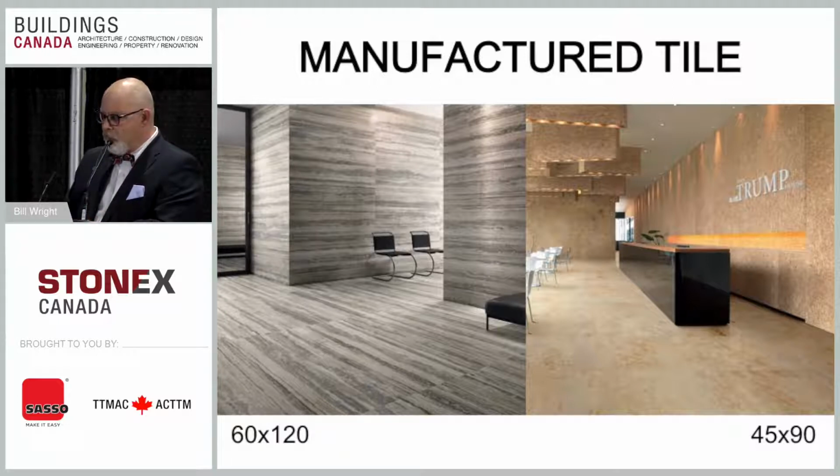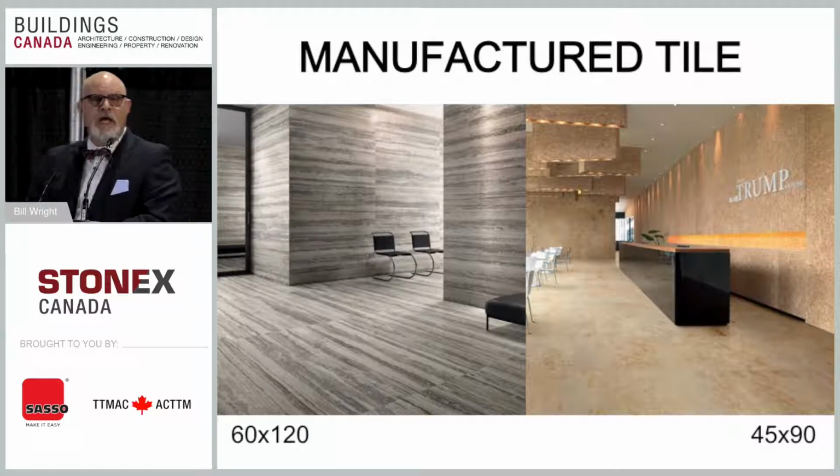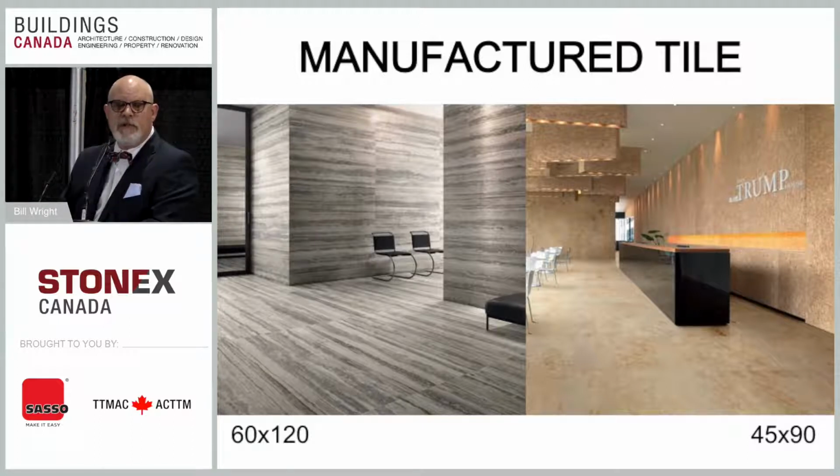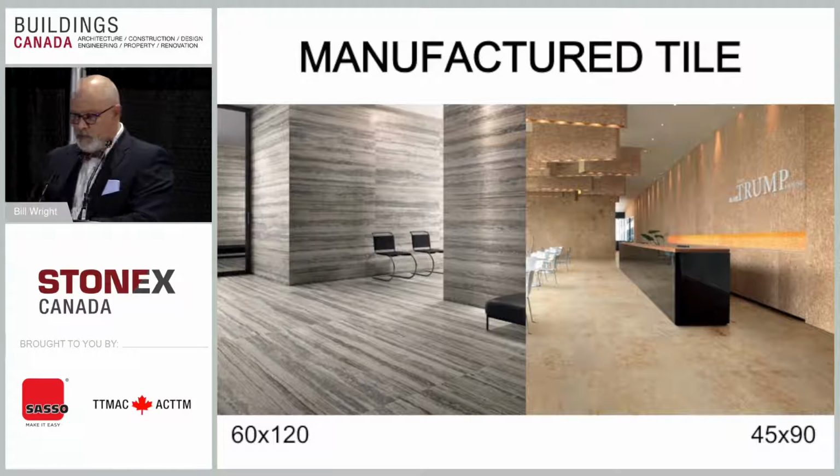What happens if we don't have the proper prep is we end up with situations like that first slide where the installer decided to use blobs or dabs of mortar to level the floor out. But as I said in the picture, it fails miserably. So it's very important, both as a specifier and as an installer, that there's proper preparation to make sure things are flat enough to install tile.